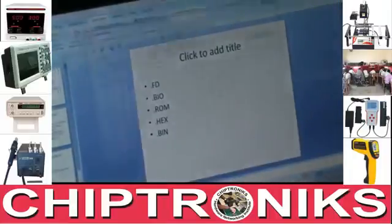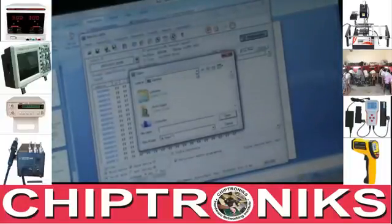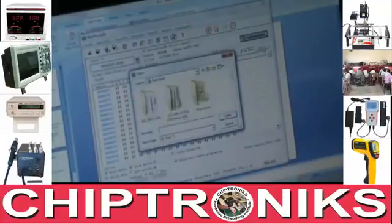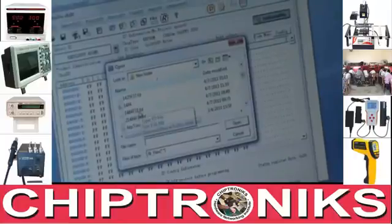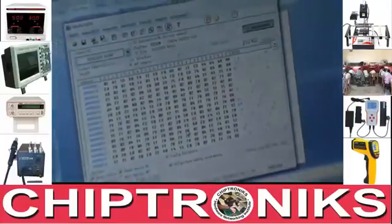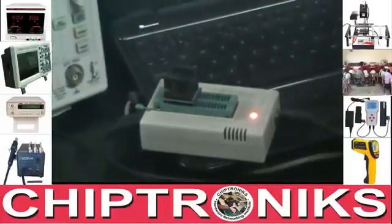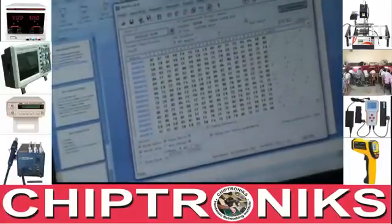Okay, now we need to program it. That's why I'll choose a file, open file. Yes, here is our file. Now I'll select the 1 MB file first because it has ICH and GMCH, and if this dual core type module is present, it has a low size BIOS. That's why I use the lowest one first. Now I'll program it.